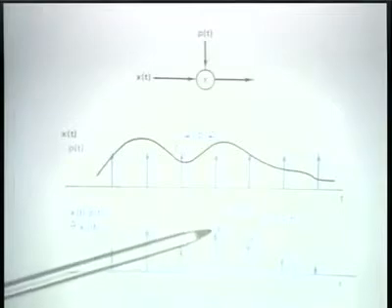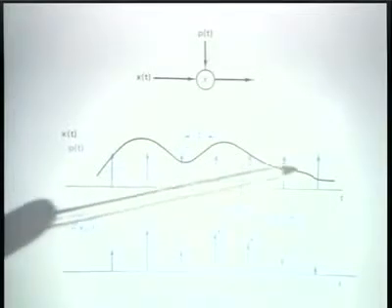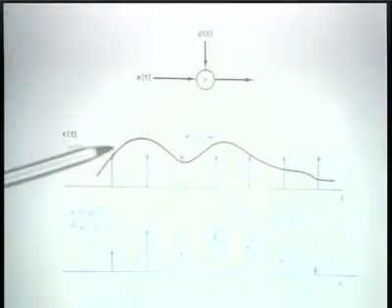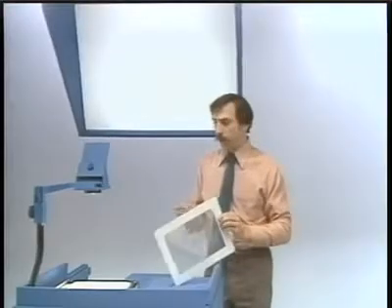In other words, what we've done in effect is taken instantaneous samples of this waveform, and the implication is that if we do that at a rapid enough rate in relation to the bandwidth of the signal, then we can recover the original signal back again.